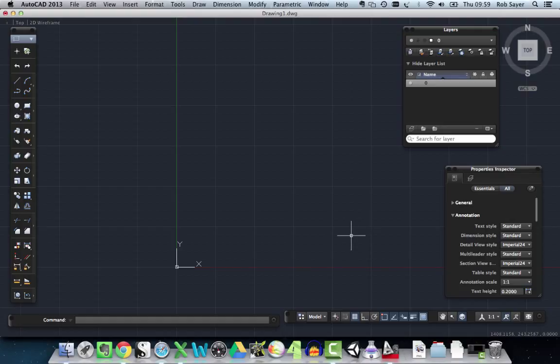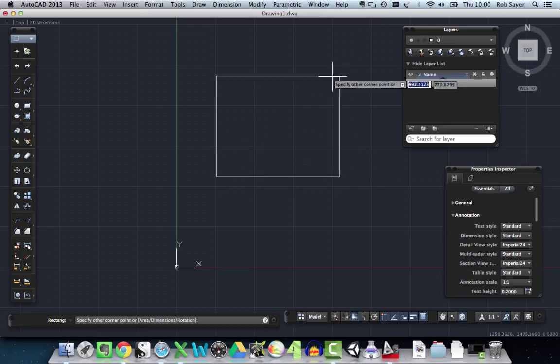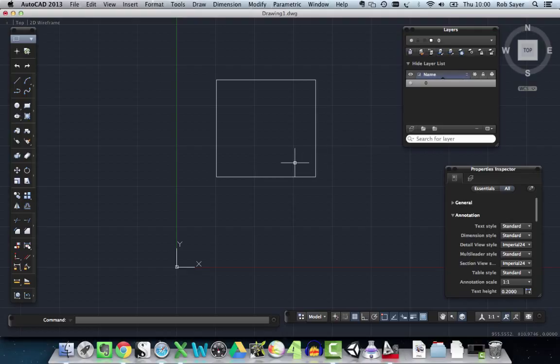of drawing. In the last video we did look at a quick way of drawing a rectangle. If you remember, we went over to our toolsets, drafting toolsets, clicked on the rectangle icon, click, let go, move the mouse to your next point, click again. That's brilliant, that's drawn us a nice little rectangle. The only thing is we didn't really have a lot of control when we drew that over the size of it. And when you're working in CAD, if you remember, it's mostly about accuracy and about putting the right things in the right place and exactly the right size. So we need more control over how we draw our rectangle.